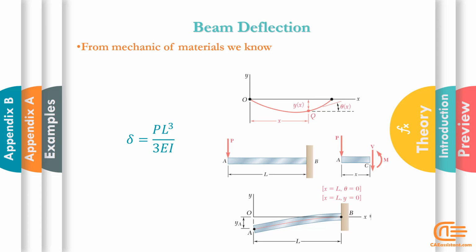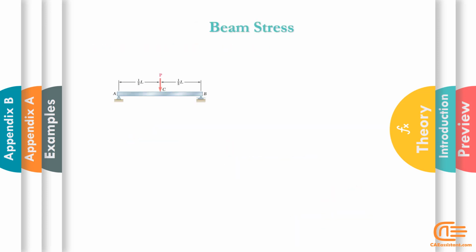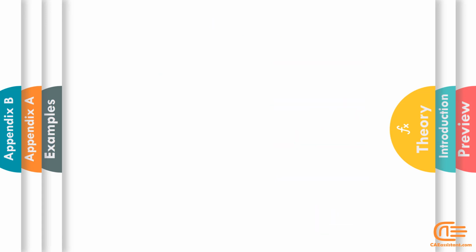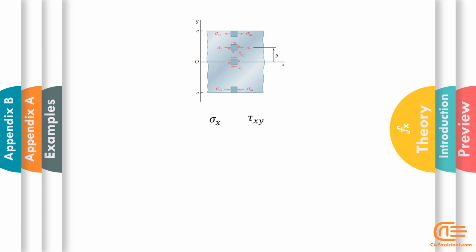The same conditions exist for calculating stress. In summary, first you need to draw a free body diagram for the beam. Then you have to get all kinds of stresses such as bending, tensile and compressive, and torsion stress, and so on. Then the results of normal and shear stresses for the critical regions of the beam should be calculated.